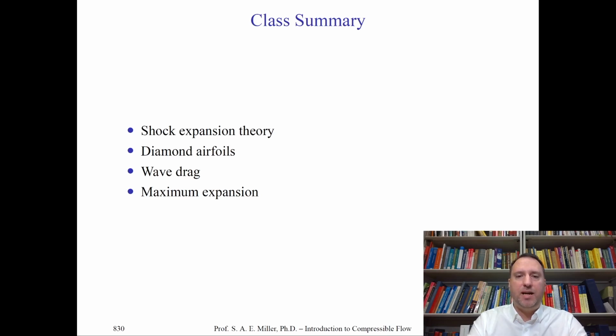We then derived and looked, with particular emphasis in historical context, at supersonic ram jets, which we illustrated through the X-43 experiment, which is nothing but the diamond airfoil cut in two according to shock expansion theory, with fuel injection and no moving parts. Indeed, this is one of the engines of the present and will dominate the future. We also looked at the asymptotic analysis of the expansion theory very briefly, and I encourage you to repeat that analysis on your own.